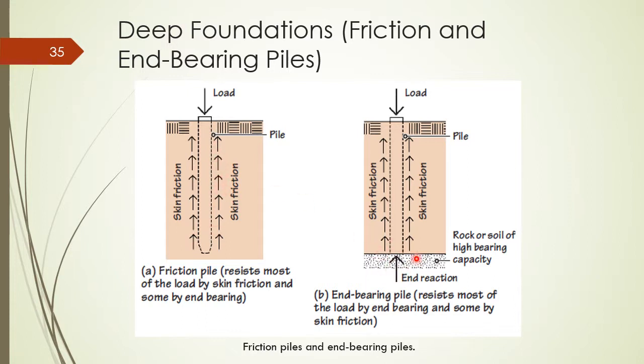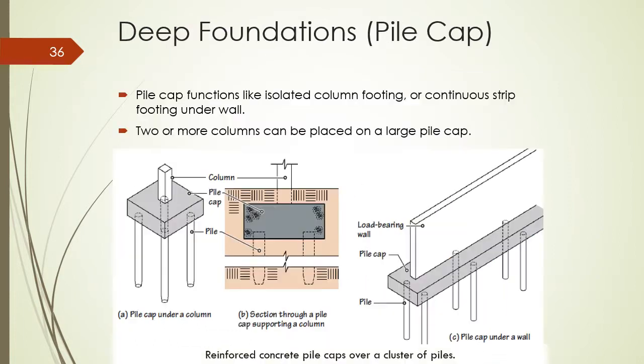End bearing, we are either on bedrock or a soil of a higher bearing capacity than above it. The multiple piles with a cap might be very similar to a long footing.